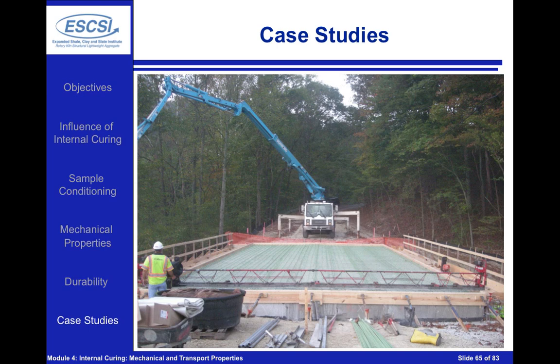So this is really important when we start to think about the role that internal curing plays. We have to not only consider the role that it has on the transport properties, but really the benefits in reducing the cracking in the system. That corrosion started within about a week, and the internally cured concretes were monitored for well over a year. No corrosion had started because you have the full concrete on the surface, no cracks.